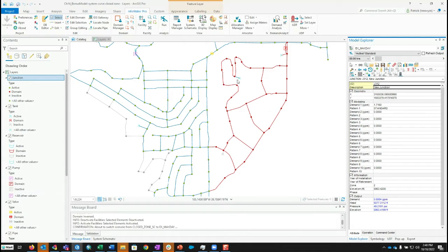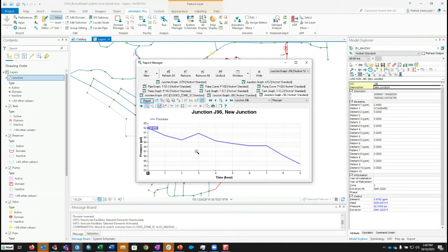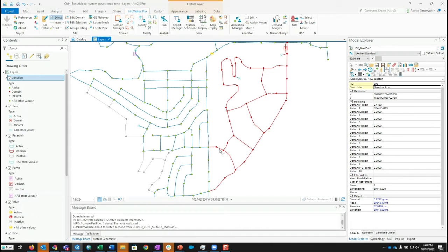So 45 psi right there, and at this location, what were they seeing? Just so that we can compare that. This one was getting down to 55, but again, this is probably one of the farther nodes. That's kind of why I ended up choosing these 2 points. This was one of the higher elevations, and this was one of the farther points.